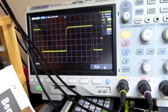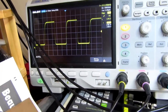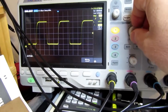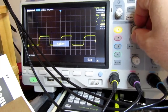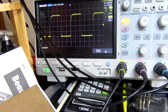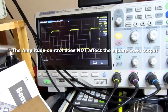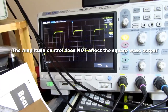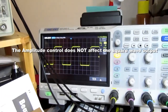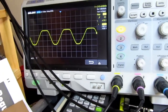When it gets down around 90 kilohertz. And what are we here? We're at 2 volts per division. And I can adjust the amplitude. Well, that doesn't do a damn thing. Maybe the amplitude only works on the sine wave output. It's not changing it hardly at all with the square wave. Sine, triangle. Well, that's not a very good looking sine wave, is it?